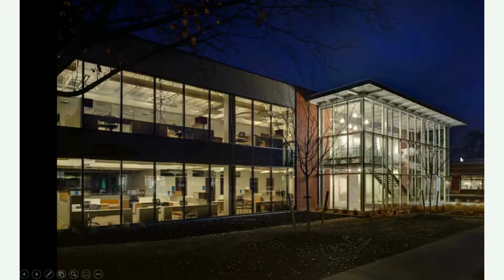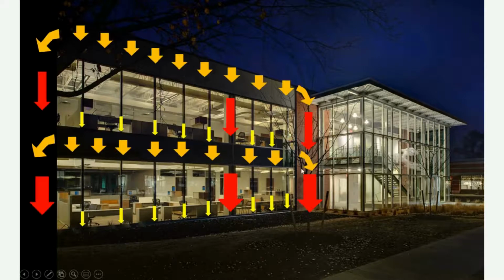Here's another couple of curtain walls, this big entrance. It's like the roof here. This roof is not carried by the glass in any way. It goes to the columns and down to the ground. The glass in this, you can sort of see it all the way to the roof. It's going to go around to the columns, down through the columns. The weight of the windows will go to the beam that's sitting right here, and it's all transferred to the ground. The windows will not carry load. So you got to be careful with that.